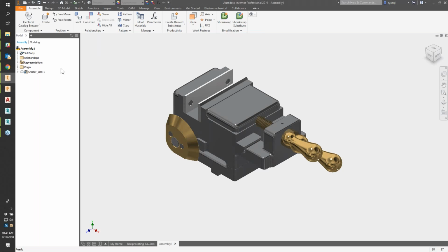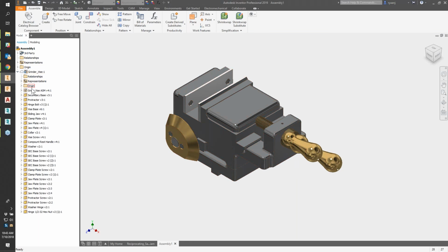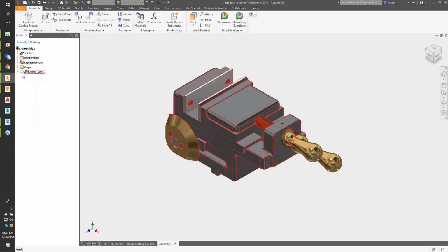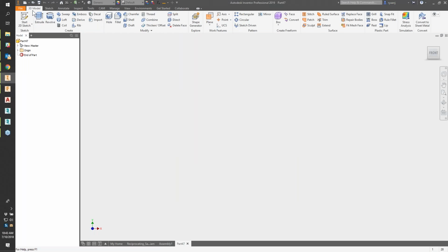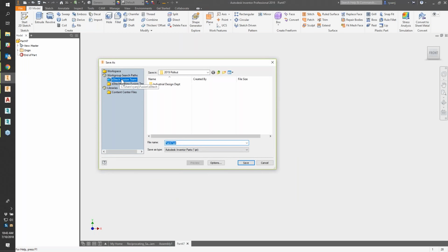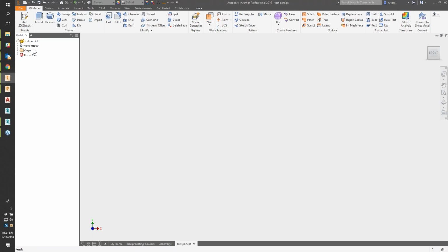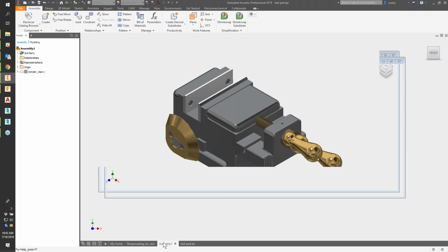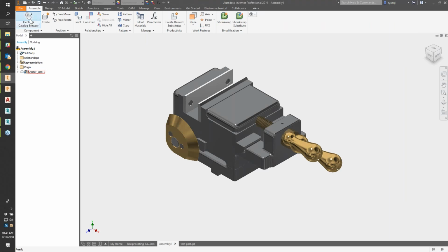And there's my design inside Fusion 360. If I expand this out, you'll see all the subcomponents listed. Another nice thing, if you've referenced something that is in that cloud workspace, you'll get an icon that it's a cloud file. Even if I create a brand new file, I go to save it, and I put it in the Fusion team, as soon as I save it there, it becomes a cloud file. So it's kind of nice. There's an indicator right there in the browser that things are being synced back and forth. Now that this is in Inventor, I could actually create a drawing from that design.